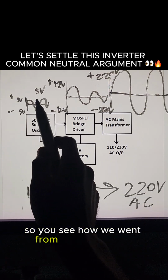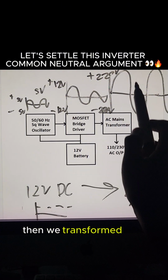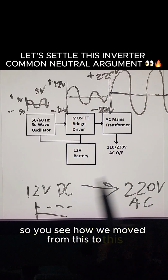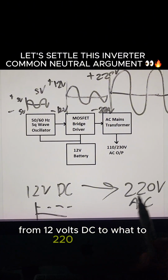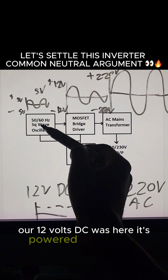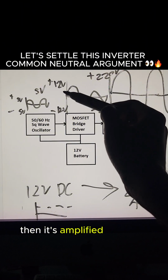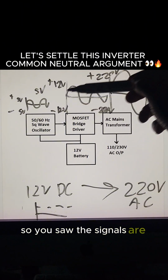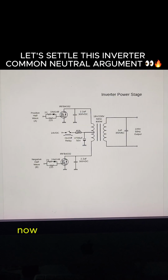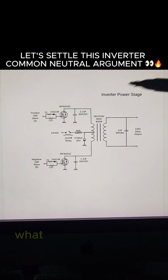So you see how we went from the small signal we generated there to the bigger one that we did the amplification on here. Then we transformed it to the 220 volts we need as our output. So you see how we moved from this to this, from 12 volts DC to 12 volts AC. So if you notice, the first thing that happened was our 12 volts DC was here. It powered the oscillator. The oscillator generated a 5 volts AC, right? Then it amplified it to a 12 volts AC. So you saw the signals are AC, AC. It was now stepped up to get to our desired 220 volts AC. Now that you've understood the working principle of a basic inverter system, let's get down to the power stage. What actually happens there?